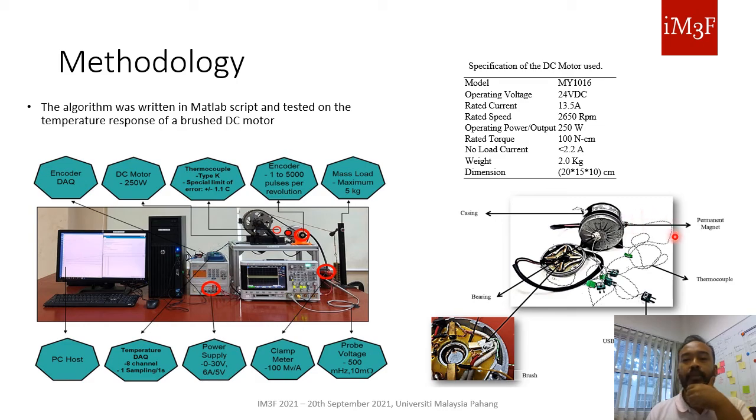It has been instrumented with thermocouple type K on various components, and then it is operated at constant speed and constant load. We have an encoder to ensure the constant speed. We have a load attached to it, and we put a constant load, and then the temperatures from the thermocouples are being measured, stored and monitored on our host PC.